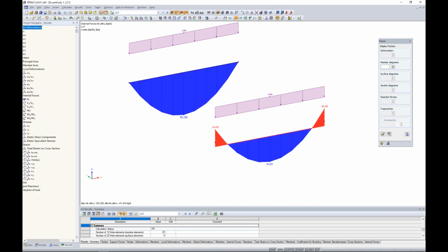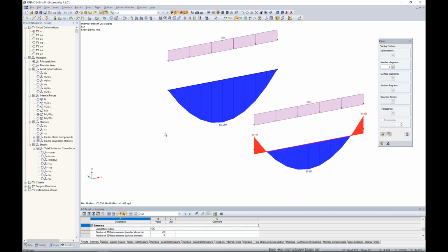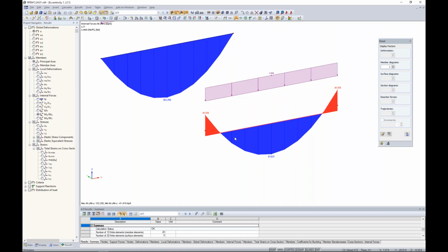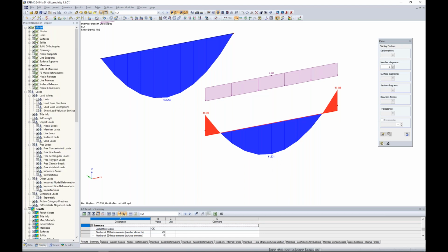We'll immediately start off with the moment diagram. For a simply supported beam, we take a look at our first example here. This is exactly as we'd expect for our moment diagram, peak moment right here at the center. But as we transition into those nodal supports, which are a pin-roller type situation, we expect no moment. Well, by introducing this eccentricity to drop the top of steel down to where our nodal support is, we now have a negative bending moment here due to those rigid elements at the end. Our peak moment in the center is almost half of what we're seeing with our original beam element.